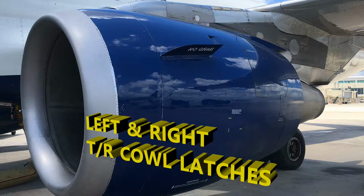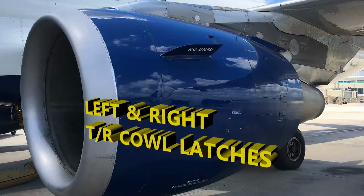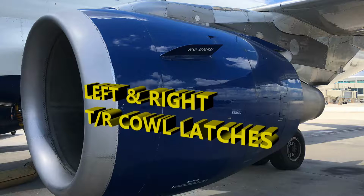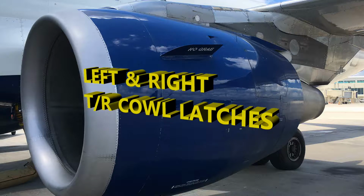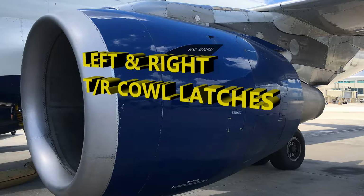But the left has different aspects to it. First of all, the latches are labeled L1, L2, L3, etc. L1 is a dual hook latch. Remember I said there are different types of latches. Latch 1 is a dual hook latch that's controlled by a handle. L2 is what's called a take-up latch, so it's like a long stroke type of latch. And then you have conventional hook latches for 3, 4 and 5 as well.